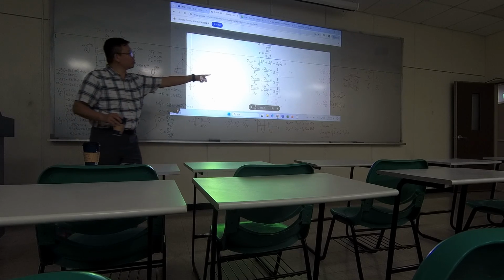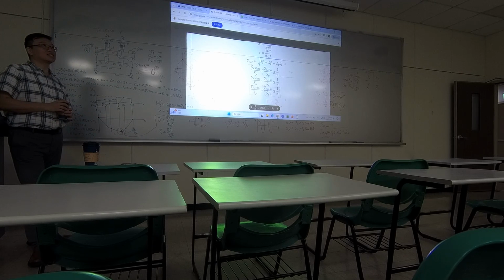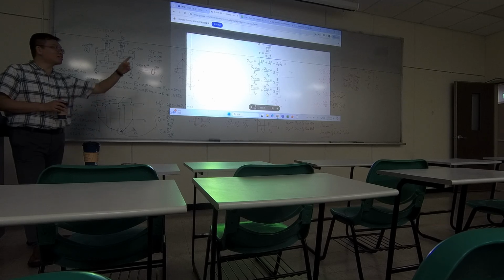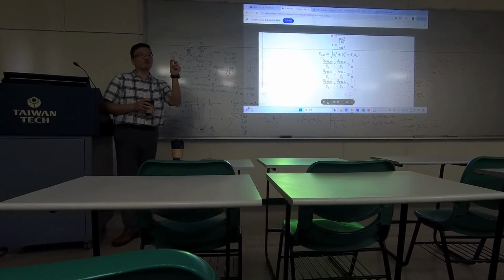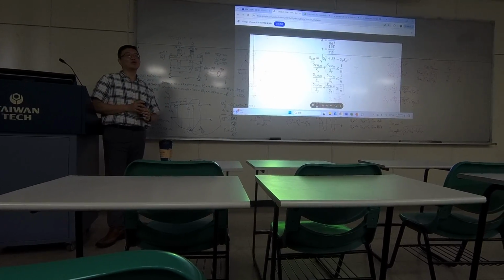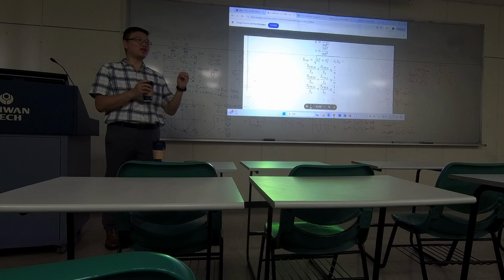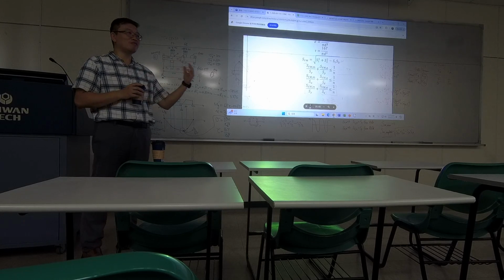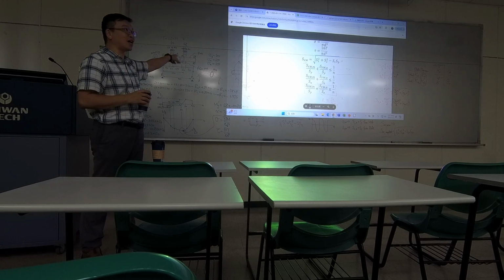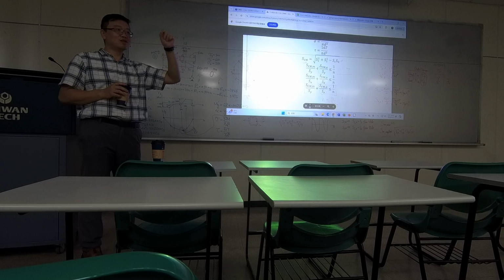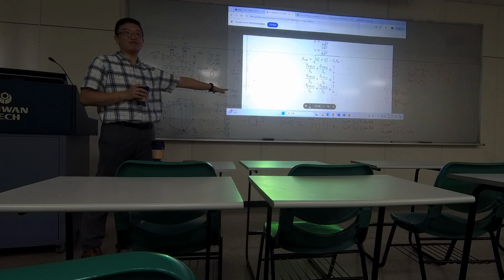So later on, when you apply the stress concentration factor, you are not applying them at the exact position. So the stress estimation will be slightly off. If you have some kind of precise measurement tool or numerical analysis machine and try to analyze the stress level at that position precisely, maybe it's not the same as what we have right now.